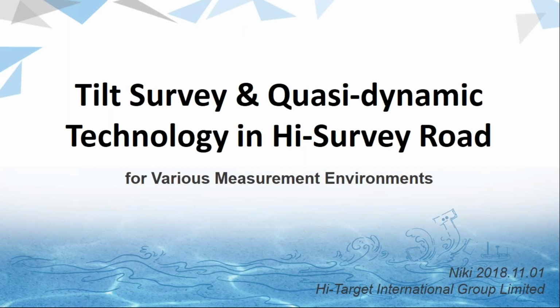This time, I will introduce the health survey and Quasi-dynamic Technology in Hi-Survey Road for you. We all know there are different survey methods for various measurement environments. Depending on the GNSS RTK data collection applications in the field, the measurement environments differ. There may be harsh situations, such as shaded areas or even unreachable points. The health survey and Quasi-dynamic technology could solve these environment problems and promote work efficiency. So this time, I will introduce these 2 modes for you.